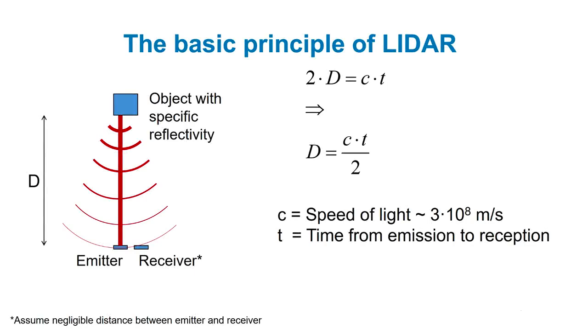The sensor emits a short laser pulse. The time it takes for the reflection to come back is then measured. The absence of a reflection means that no object with enough reflectivity was present in the path of the laser beam. Knowing the speed of light, the distance of travel of the received pulse is easily calculated. However, there are a number of challenges to address.